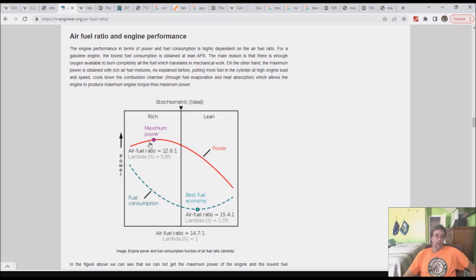Well, if you go down here to maximum power, you have essentially run into a knock situation. So to overcome the knock, you put additional fuel into the system. The fuel does not actually burn. It's there to absorb peak heat during the portion of the four-stroke cycle where you hit maximum pressures during and just before burning.